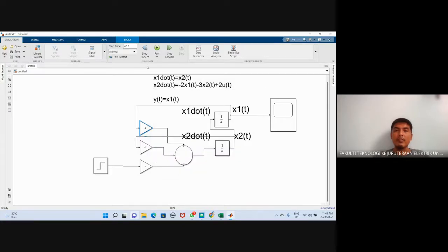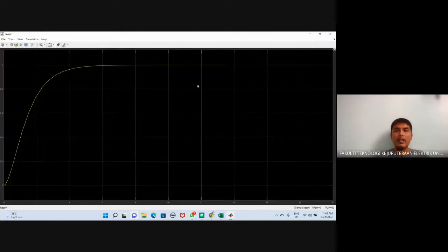So I change again to -2, with the pole on the left hand side of the plane. So the system will become stable again. I make it about 20 seconds. But it's quite a long time. Okay, so it becomes stable again, because I changed back the pole location.